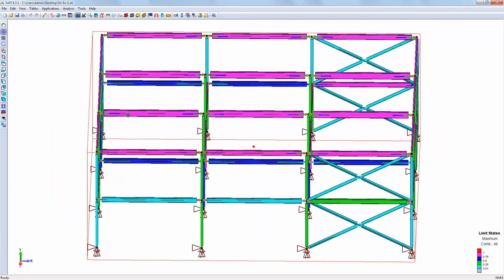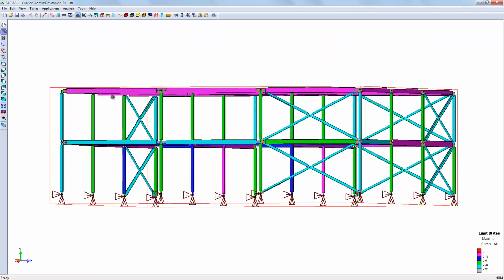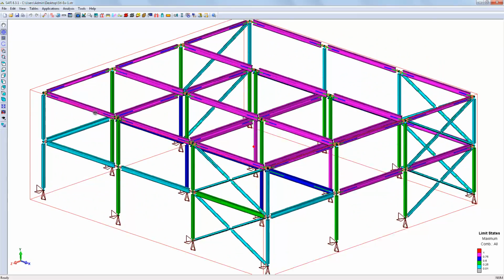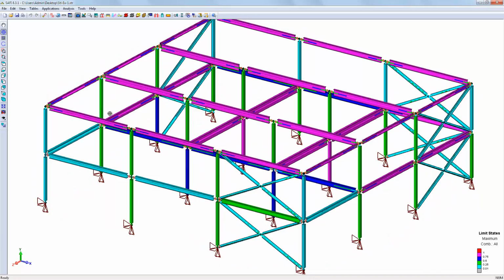You may rotate the view by clicking on the structure and by moving the mouse while keeping the left button of the mouse pressed. Release the button at the end of the rotation. To set the rotation around a particular axis, click on the right button of the mouse on the structure and select the desired option. The current option is marked with a check.